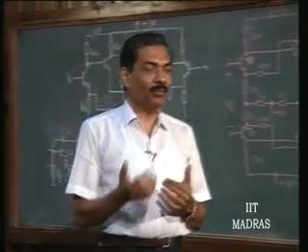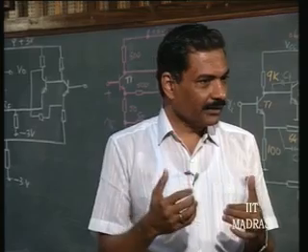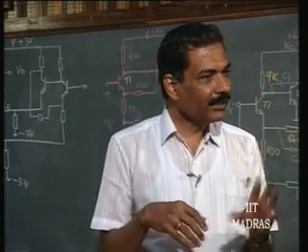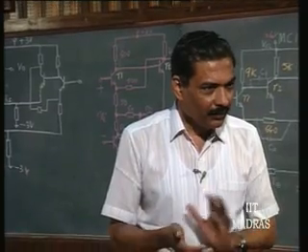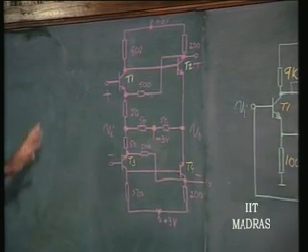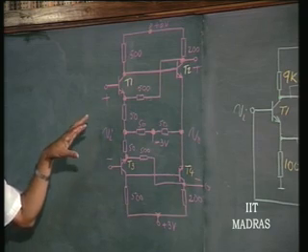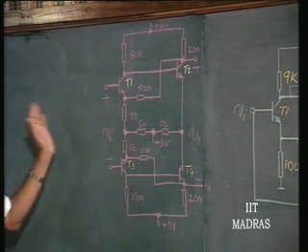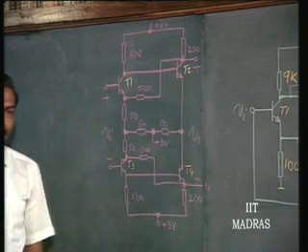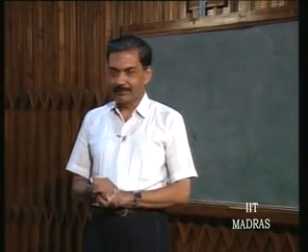You see, already we are getting into problems, that the IC might give you trouble. The previous ICs that we have discussed would have never given you such trouble, but we had to live with low value of loop gain, and consequently somewhat it is going to become sensitive to supply voltage and temperature variations. Okay. So, we had just seen how a H feedback circuit starting from fundamentals could be converted into a useful IC with biasing etc. taken care of very well. So, that configuration that we have synthesized transforms itself into a very useful integrated circuit component, wherein externally we might have to do some amount of fiddling with it, okay, in order to make it work for the optimum bandwidth. Okay, this is an important thing.